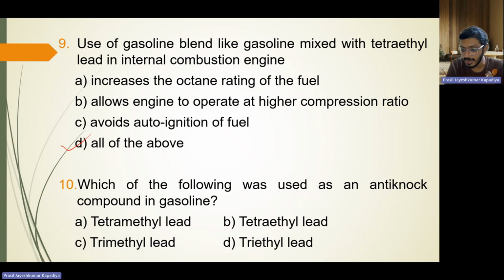Then one more factor is advancing the spark. Advancing the spark will result in more compression during the sparking. The increase in temperature during this sparking will be higher, and hence the tendency to knock will increase. And so by retarding the spark, the tendency to knock will decrease.